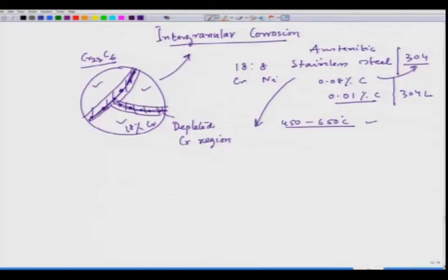So, now the typical situation is that we have two situations. At the center region we have chromium oxide, and around this region we have chromium oxide, but in this region we do not have chromium oxide. Since chromium oxide is cathodic in nature as compared to the iron surface with depleted chromium, the cathodic reaction would happen wherever we have chromium oxide.